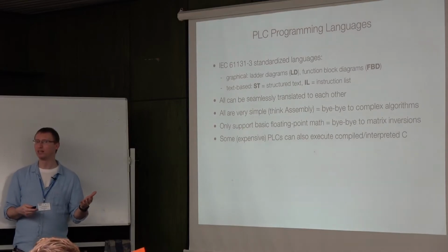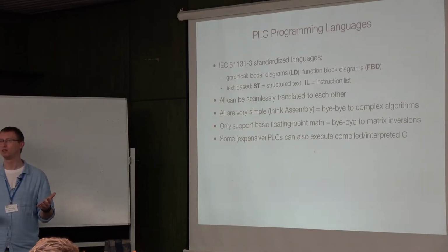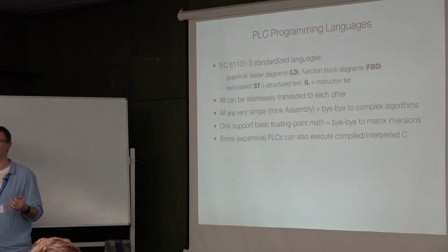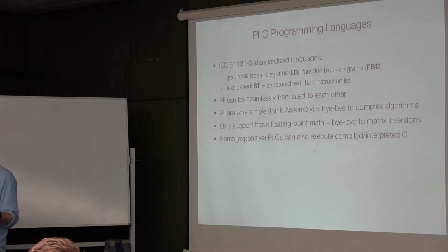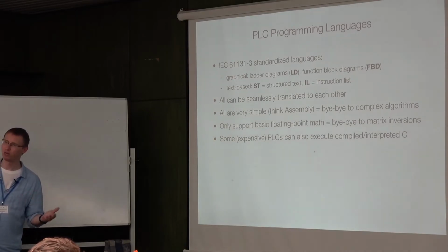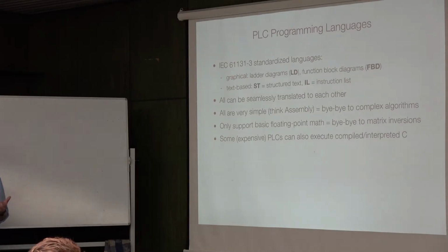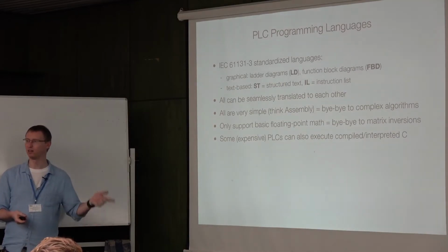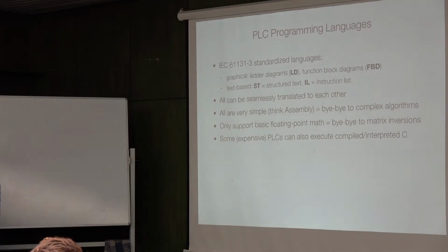If you invest more money, and it's not the control designer who invests, it's the operator of the control system who decides. If for any reason he is nice enough to you, he buys more elaborate hardware, maybe you can get C running, maybe you can take your active set methods. Yes, there are PLCs like that, but then I wouldn't even call them PLCs, they are just industrial PCs. So by PLC I really mean something like 8 kilobytes of memory programmed using these pesky languages. That's how things are done.